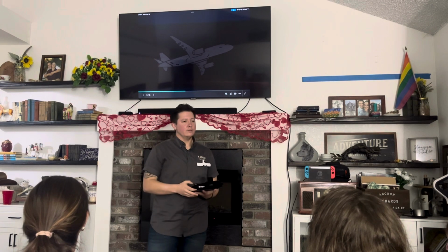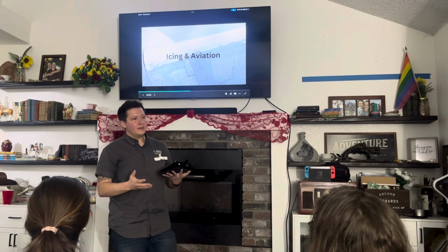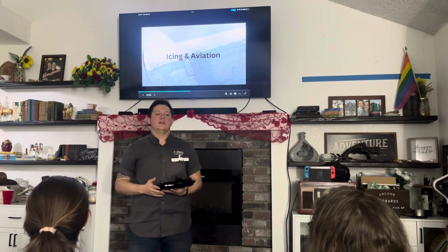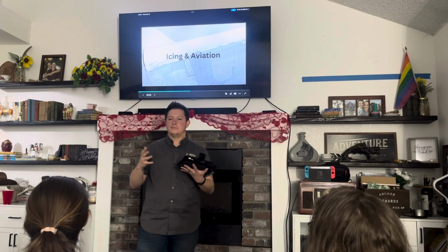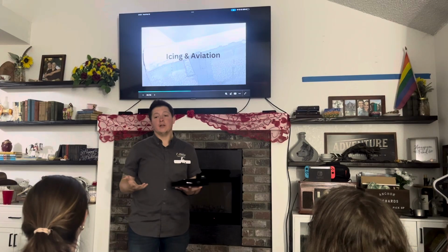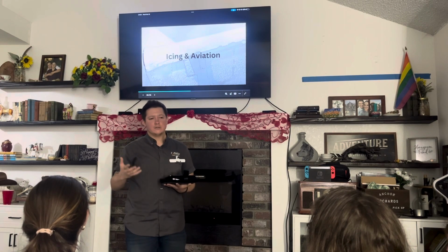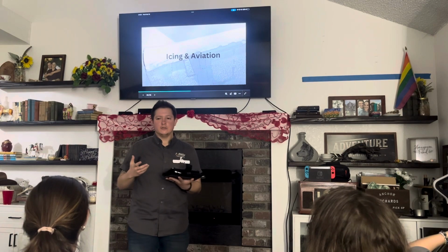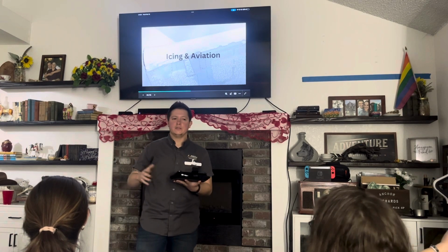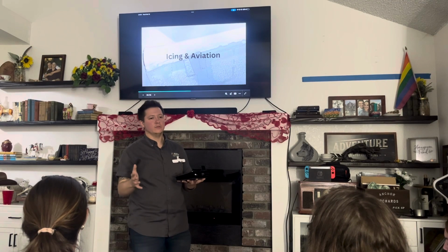So let's talk about some airframe icing. Airframe icing, a little bit, it's not too dangerous. As it starts to accumulate, our weight's going to increase, right? Maybe it'll increase so much that we're just going to fall out of the sky. It's actually not what happens. I mean, it does increase our weight, but what it's actually doing is, as it accumulates over the wings, it changes the overall wing structure or the surface over which that airflow is going.